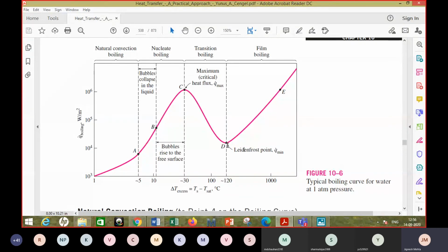So the heat flux is not very high there. Why is the heat flux not very high? Because the temperature is very high. The moment the liquid water touches that surface, vapor is generated, and that vapor becomes a resistance to the further heat flow from the tawa surface to the remaining liquid. So the liquid is able to retain itself for some time and move around here and there, and then it boils off, right? So that's the Leidenfrost effect, because of the low heat flux that you get at the Leidenfrost point. Okay, and then the right-hand side part is mainly film boiling.